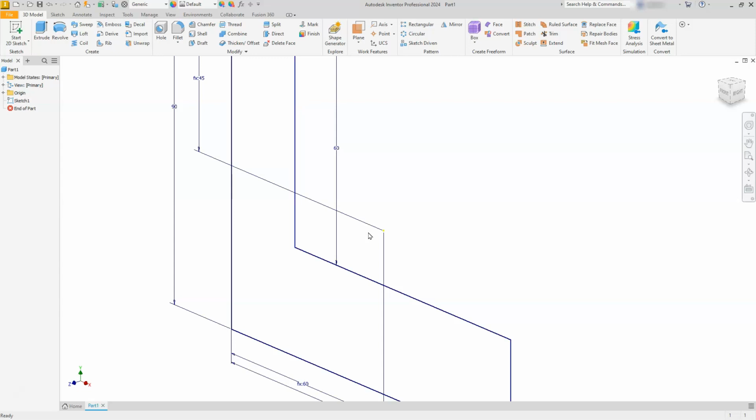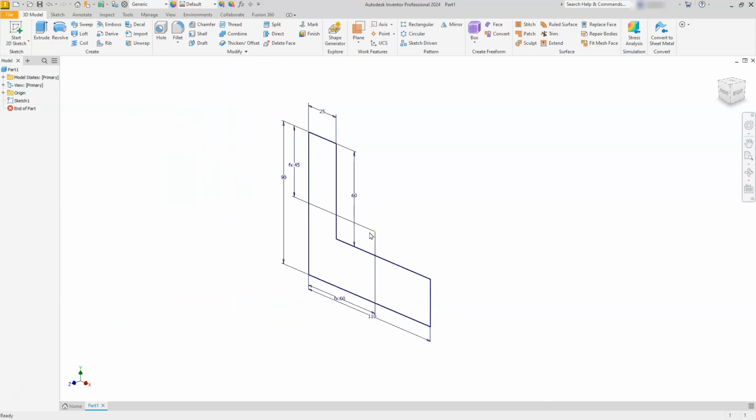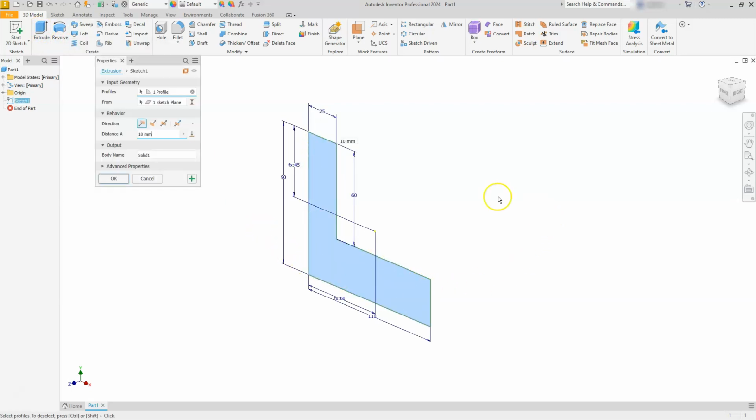So, in case you get a little mixed up on it, scrolling in and out on this is going to change things. Okay? So, just remember that it's backwards. Once I've done that, I'll go ahead and hit the extrude icon, and you're going to see that this shape will automatically highlight. The dialog box should come up, and the shape will already start previewing some kind of extrusion.